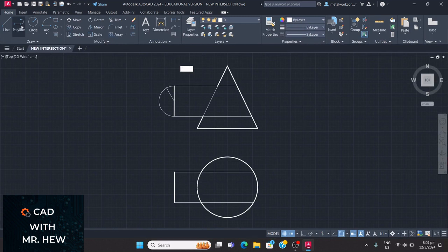All right, so we're gonna repeat the process. So we're gonna go line, center, and the length would be 62, and the angle would be 150. Enter. All right. Now we need a horizontal line going across, so we can press enter to get back the last command. Click there, turn on ortho, enter. All right.